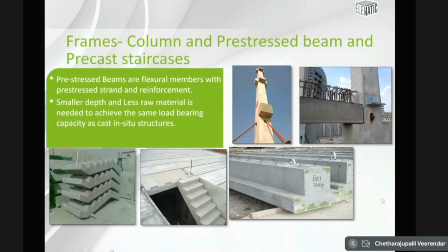You should remember that no precast building is 100% prefabricated only. There is going to be wet works. About 15 to 20% of the work is wet work. That means we are going to place the slab on this junction. For example, this is the inverted T beam. The slab will come here. There will be a lot of reinforcement on top, and then we are going to pour structural concrete on top of this so that the slab and the beam all become monolithic elements.